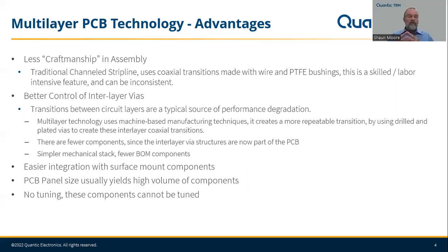The other thing is that once you have a board-level design that has all these interlayer transitions designed right into it, you can have a very clean launch off of boards that are made to be surface mount components onto their carrier or motherboard. This way we can get a good, reliable, and predictable transition.